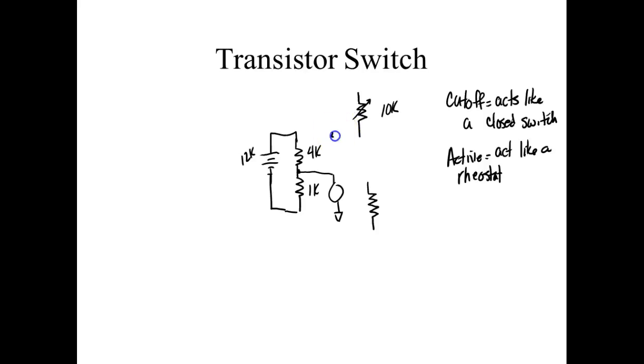Well, this guy right here would drop 4/5 of the voltage. This guy down here would drop 1/5. Okay? So how much voltage would be across the 10K? Y'all know what we call it, did they teach y'all the voltage divider formula? Yeah, that's a neat formula because you don't have to solve for current. And most of the time when you're dealing with 2 resistors, you can calculate RT in your head. Okay.